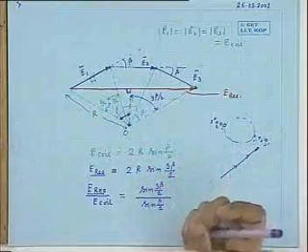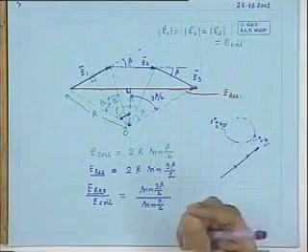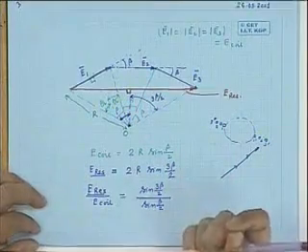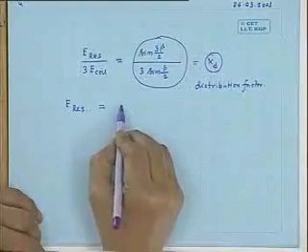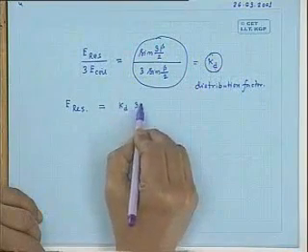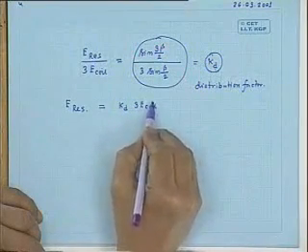Therefore, because of distribution, you sacrifice something. The voltage available becomes lesser. By what factor it is less compared to the case when the coils were not distributed is known as the distribution factor. Okay. So the distribution factor is this one, Kd. That is, E resultant is Kd into 3E coil.